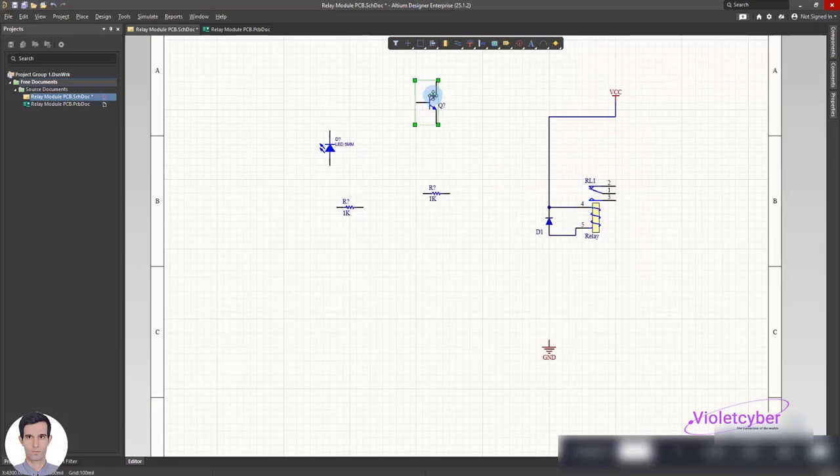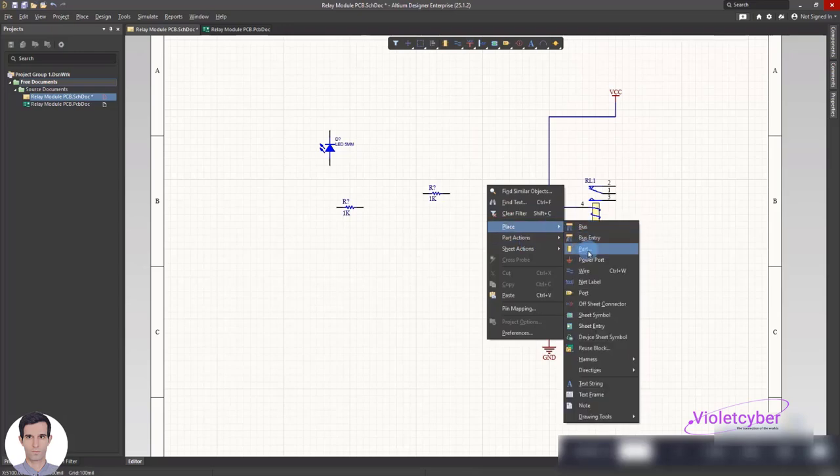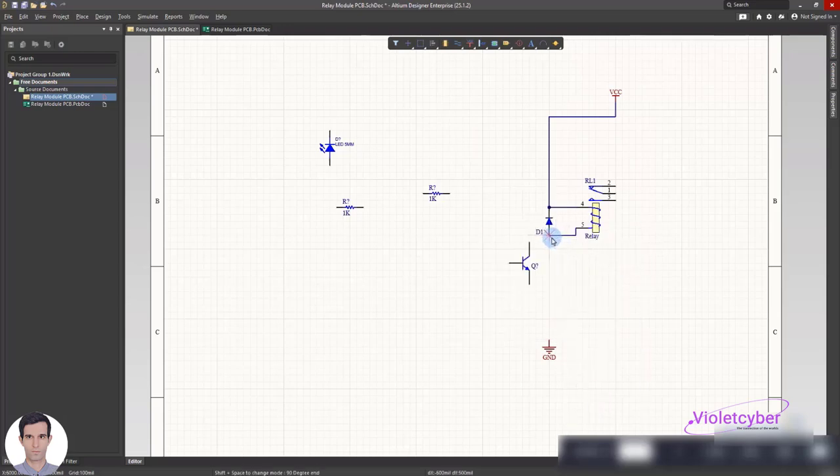Now what we need to do is to put the transistor in its proper place. Always keep the schematic clean and uncluttered. So our transistor is going to be like this, and will be connected to the anode side of the diode. Well, you learned the reason, of course. He explained it again. So we connect it using the wire like this. You see the positive current comes from there, enters the relay pin and passes through the transistor, wants to connect to the ground pin. But because the transistor acts like a switch, it doesn't allow it to. In fact, this base side is connected to the ground pin unless it receives a signal, and this is actually the principle of the operation of our relay.